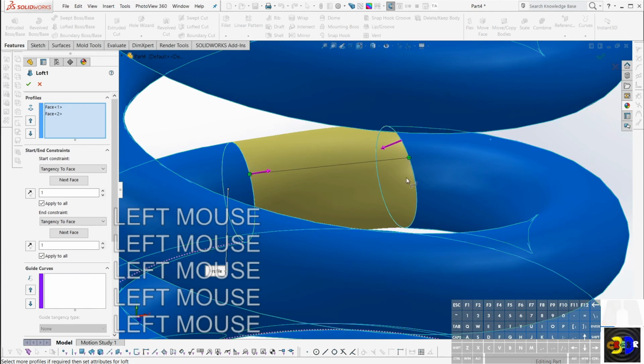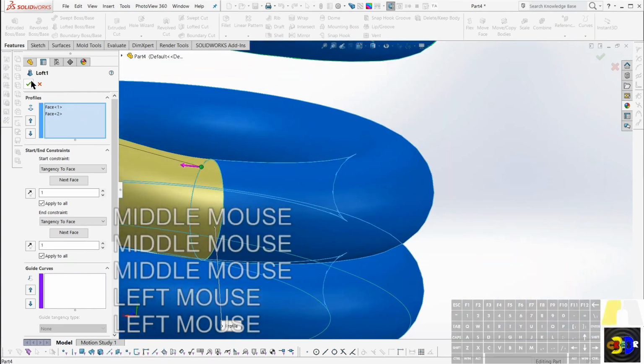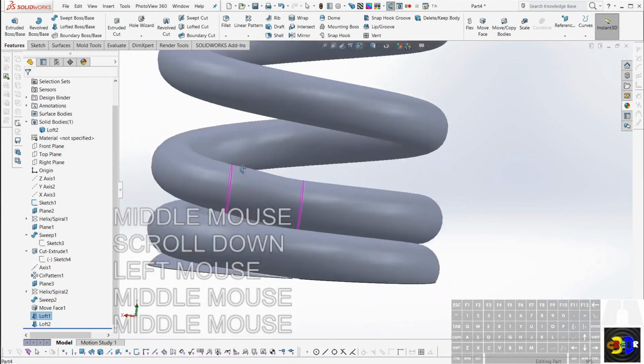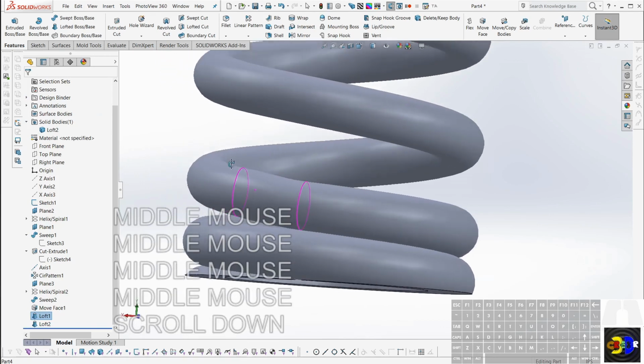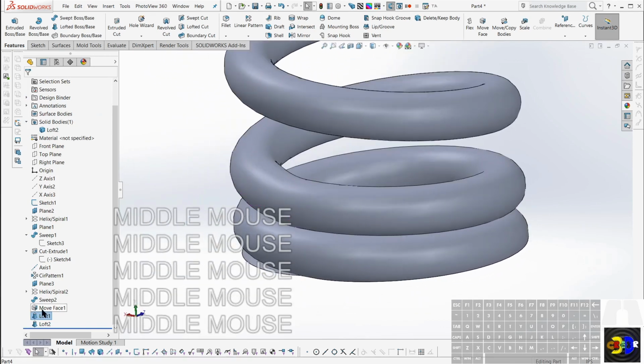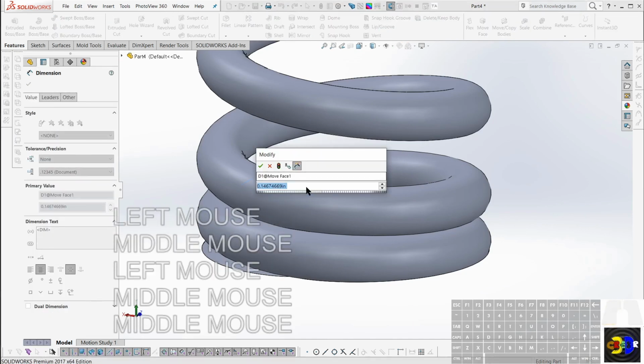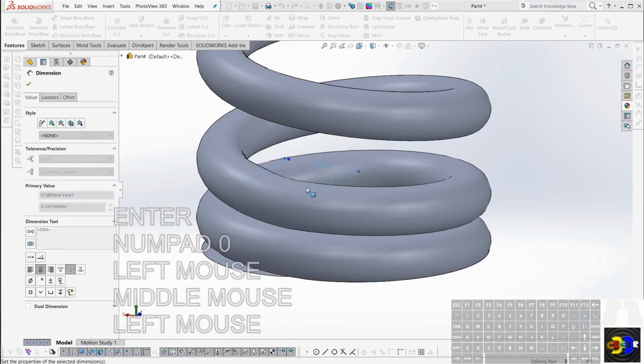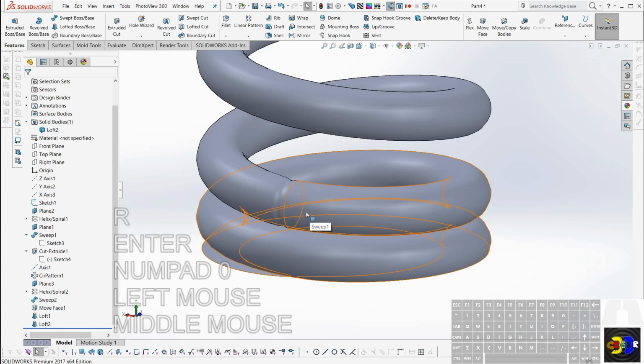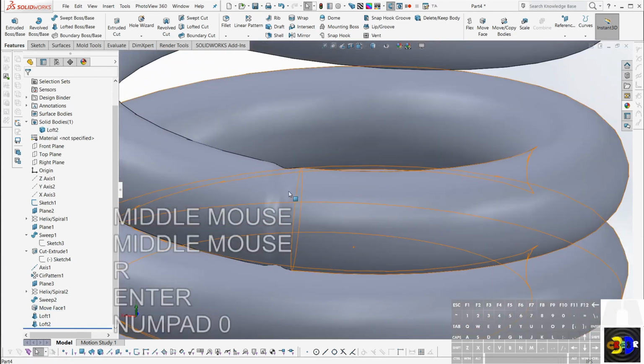That's probably pretty close. But it's still a little goofy. You can sort of see it's a little wavy, and so we'll just make this initial move face a very small number. Let's call it 30 thousandths of an inch.